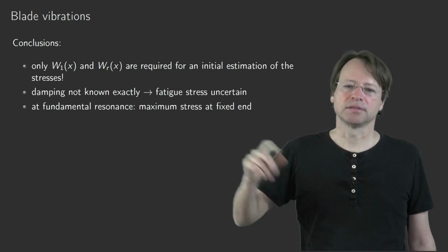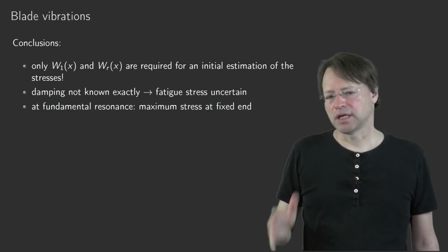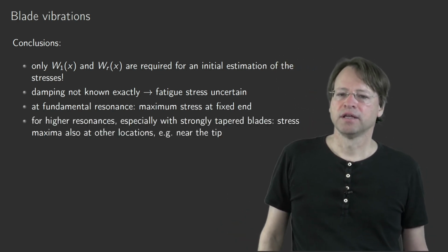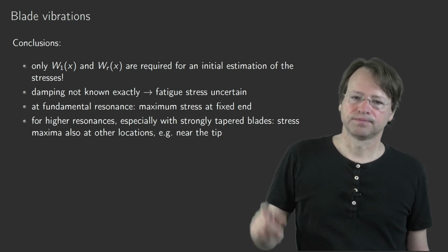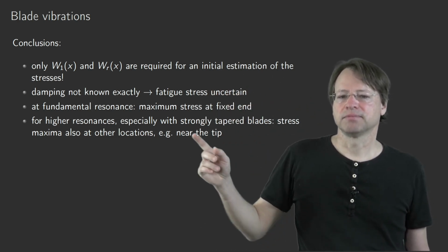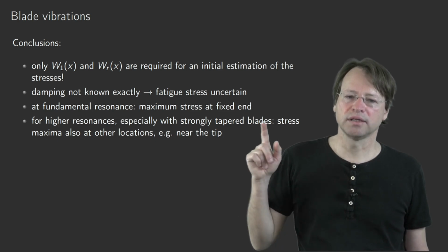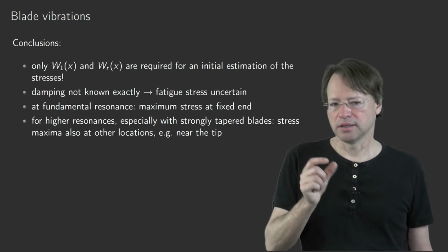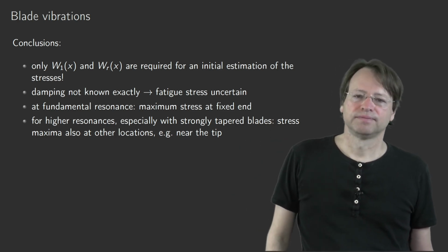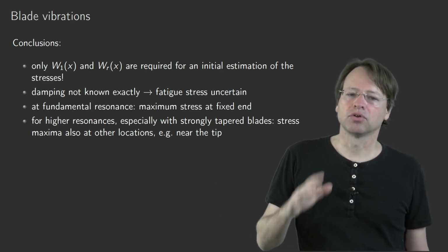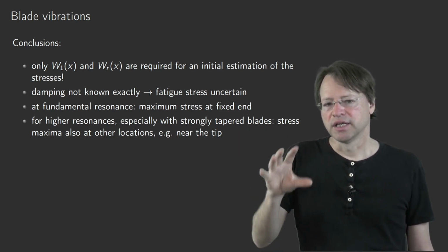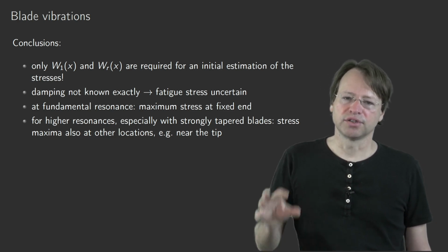And of course, there could be some other modes that are in resonance, or higher modes that are in resonance, and then it's not sure that the maximum stress really occurs at the fixed end. So for higher resonances, and especially for tapered blades, the stress maxima can be at other locations, and there is one other location that is very sensitive, not only to stress, it's the tip, but also to uncertainties, namely also to geometric uncertainties in that structure, because what we assumed here is a